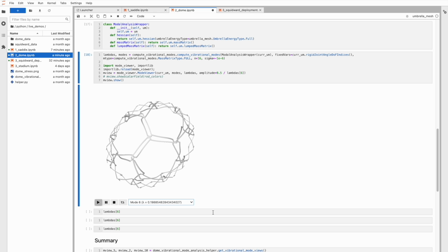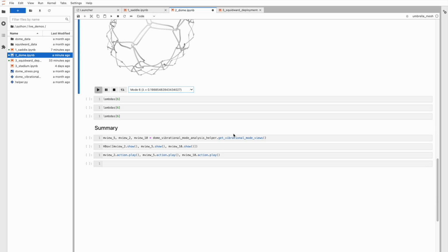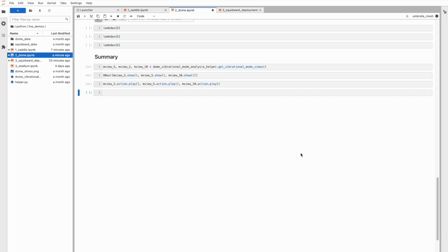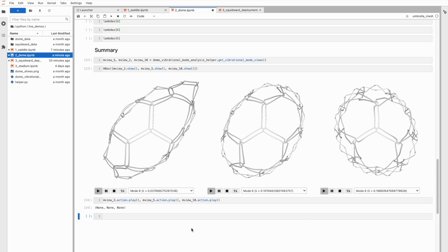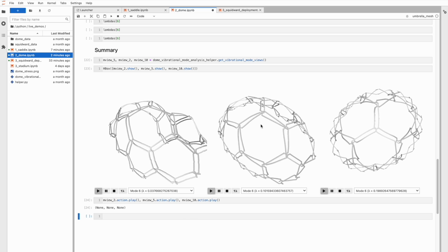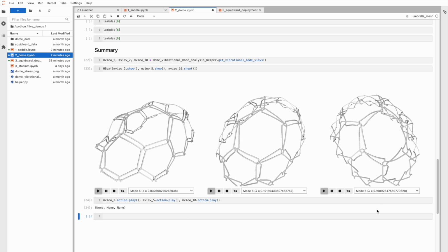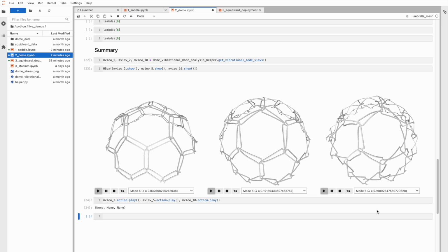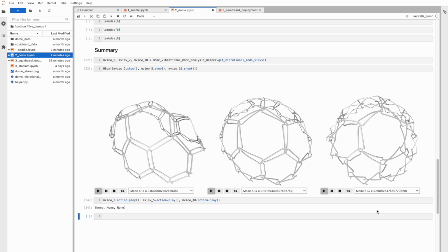On the other hand, if I decrease the plate separation and decrease the depth of the deployed shell, the stiffness also decreases. In the summary view, you can see that as we increase the structural depth by increasing the plate separation, the stiffness increases and the structure deforms less.